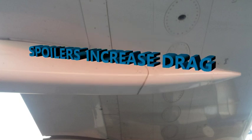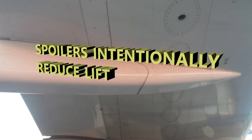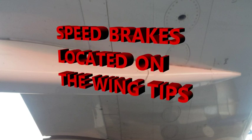And then same thing with the spoilers. Remember I mentioned spoilers a bit ago. Those are also creating drag when it's needed. The main thing here is it's intentionally reducing the lift. That's usually right before touchdown. Those plates on the top surface of the wings can be extended upward into the airflow so that it's spoiling that lift. You also have speed brakes that are located on the wingtips.